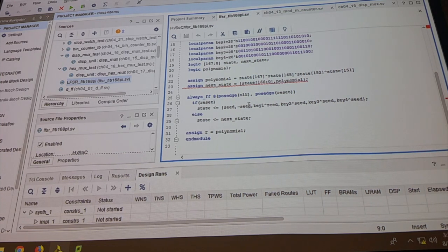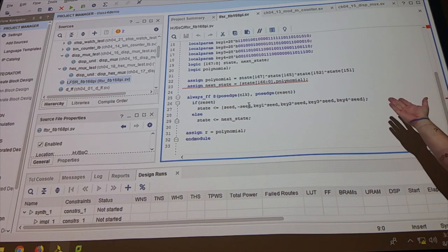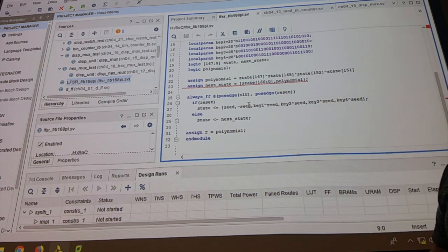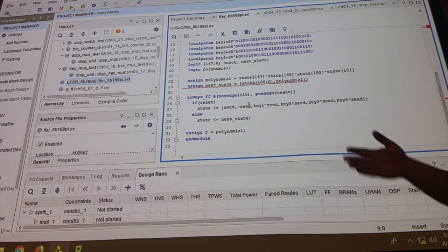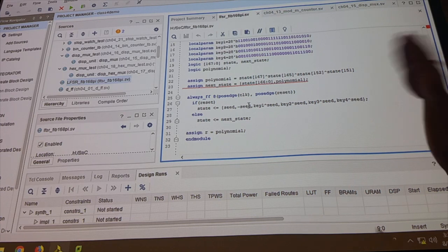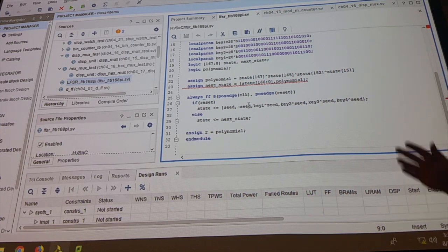So, this is one way, this is fully synthesizable. It's a flip-flop, simple polynomial calculations, away you go. Right? And when you simulate it, you can do a real simple test file for this: give it some, pick 28 bits as a seed to put in, give it a clock pulse coming to it, and just watch the output. And you'll see it'll mix up quite nicely.